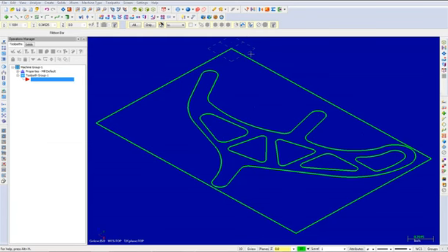For Mastercam to create proper toolpaths, the geometry has to be chained. You will have to select chains of entities which consist of one or more entities linked together in order and direction. Problems such as overlapping entities, duplicate entities, and untrimmed entities can result in gouges or unmachined areas. In the next step, you will learn how to clean up the chains.